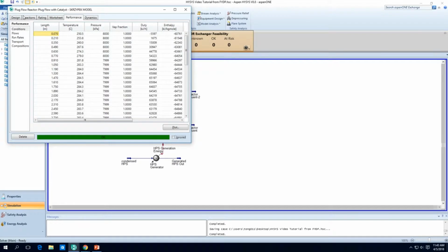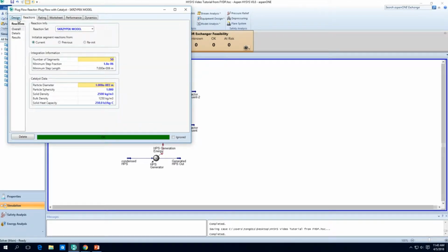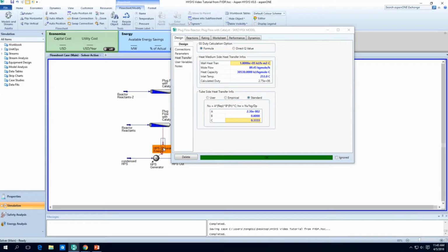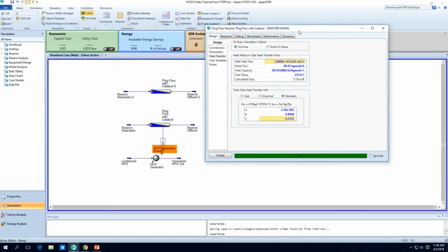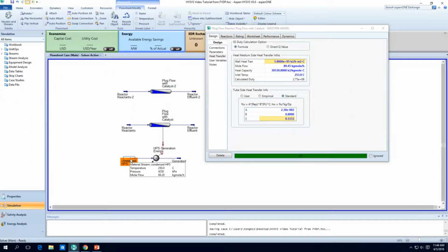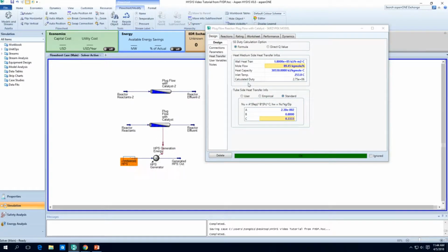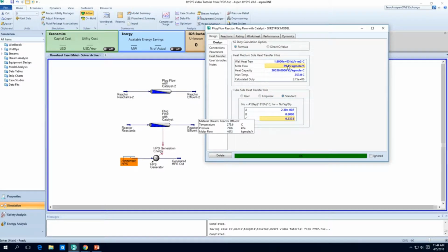And of course, in the last video we also quickly went through how to calculate the heat transfer coefficients. So for the QA, the Q equals the UA times LMTD. We talked about the wall heat transfer coefficient and the heat capacity, etc. All these and the Nusselt number will be used to calculate some kind of energy flow. We have to make sure this outside steam molar flow rate closely matches this molar flow rate here. So this is at 8920, this is at 8945, so it's close enough.